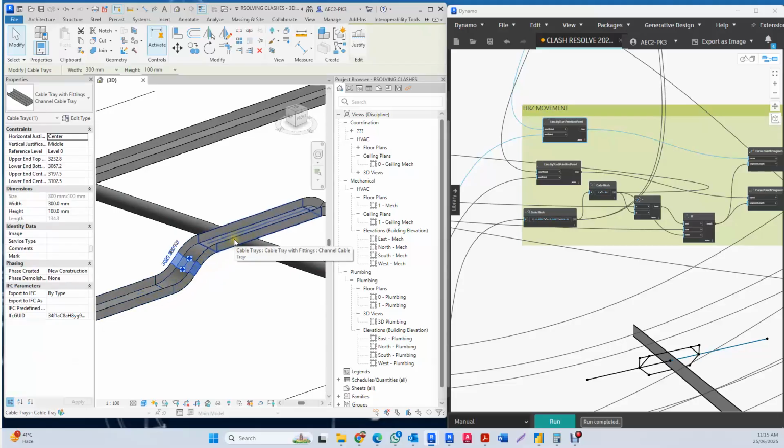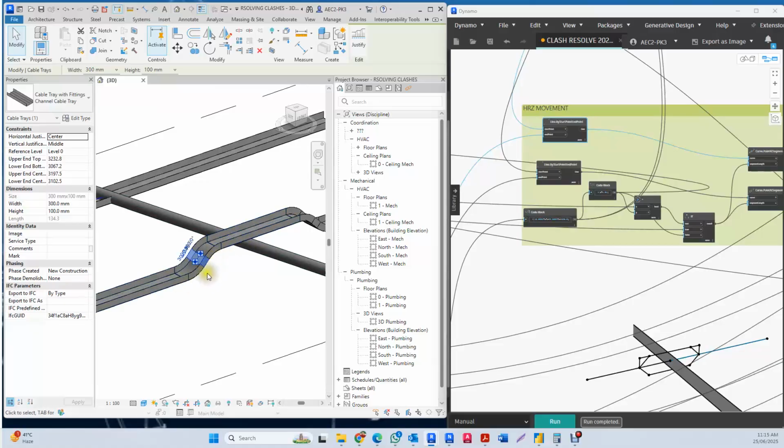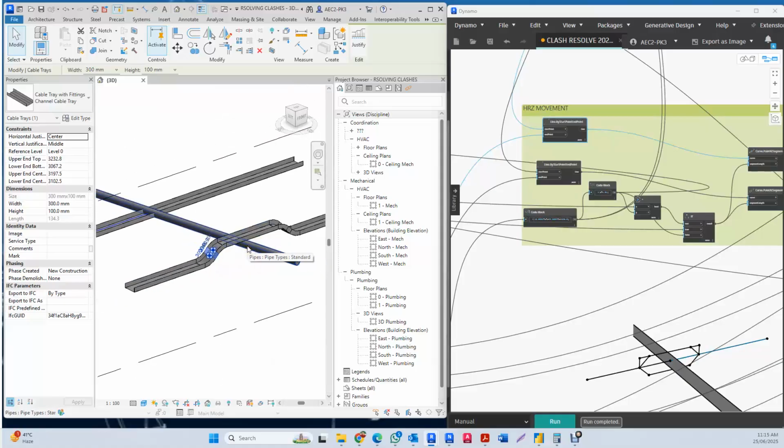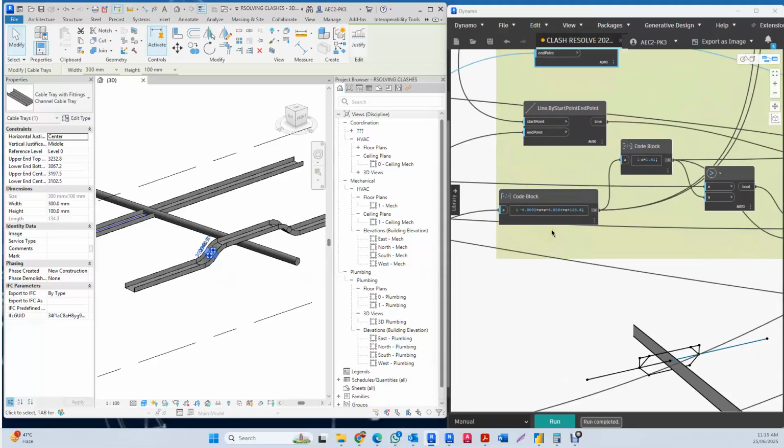And if you create the Dynamo script and make this distance small, it will not work. It will give you an error. So that's why this distance from the middle to this one is very important. By trial and error, I tried to make it, and I created an equation from trial and error to understand how much is the diameter of this one, how much is the distance of this one, how much is the height, and make it in one equation.